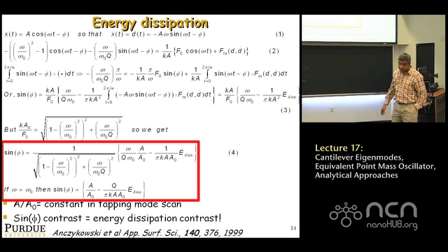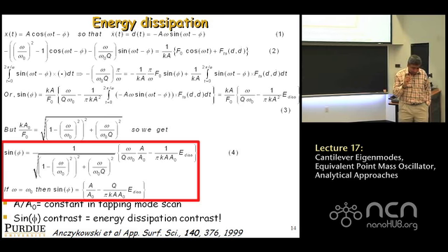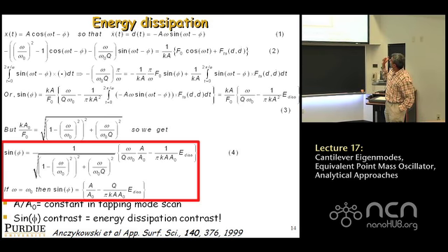Now, if you think about that integral term, think a little bit about the term inside the integral. The quantity negative A omega sine(omega t minus phi). What is that? Negative A omega sine(omega t minus phi). If you think about it from equation 1, it's the tip velocity. Everyone with me?